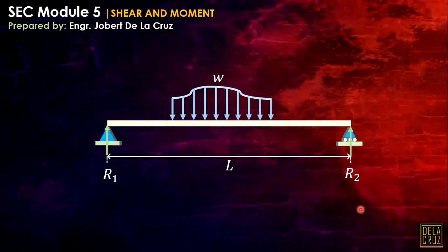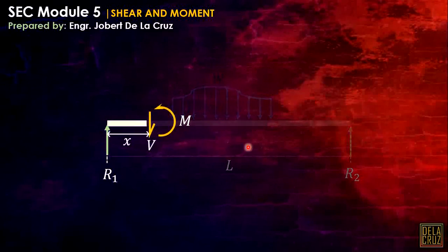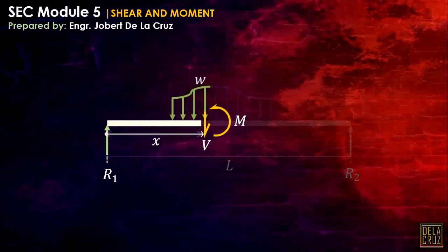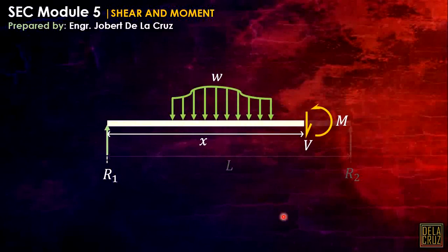Okay, so for shear and moment, we'll be considering two points or a segment by segment. We can use the equation method or the area diagram. Imagine this beam, we will be cutting it at this portion, and then the shear and moment will be exposed. This can be solved by equilibrium. Another segment here where the load is included, of course another equation can be formed here, because we have additional load. And another segment, another equation there.